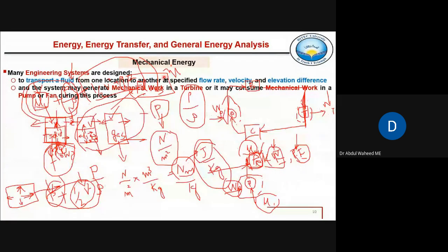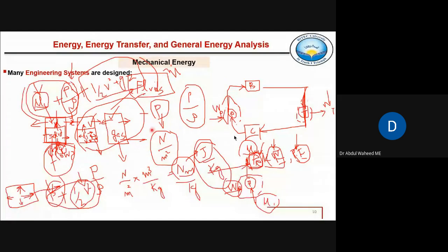और in case ओके, अब मैं आपको बताना, हम कह रहे थे what is mechanical energy. So mechanical energy is only this one, P over rho, pressure energy plus kinetic energy plus potential energy. These are pure mechanical forms of energies. U is not mechanical energy. So pump में या turbine में, hydraulic turbine में, what we have only mechanical forms of energies are changing from inlet to outlet. Internal energy do not change. ठीक है, इसलिए हम इसके effect को यहाँ study नहीं करते pumps, hydraulic pumps में और hydraulic turbines में.